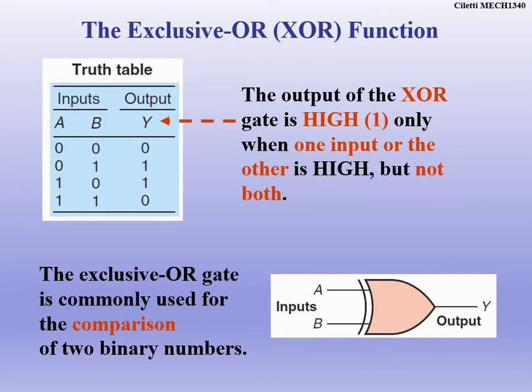So when we use an XOR, this is normally symbolized as an A plus B with a circle around the plus sign. So that's even on the Siemens test. So make sure that you know that. That's going to look like A plus with a circle around it B. That means A exclusively ORed with B. What does that mean? That means as long as one of the inputs is high, one of them has a 1, we will output a 1.